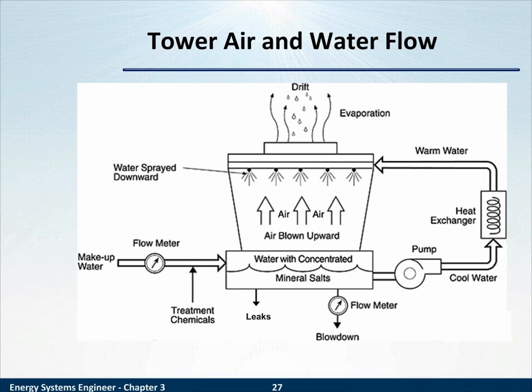It's worth a minute to take a pause here and see how the cooling tower works and what it does. We'll focus in a minute on the water balance in the cooling tower. But now just look at the diagram and see the air blown upward. You see that the cooling tower, this one pulls air up through a fan, and in a counter current, warm water is sprayed down onto that air. That warm water interacting with the air causes water to evaporate. When water evaporates, the remaining water is cooler.